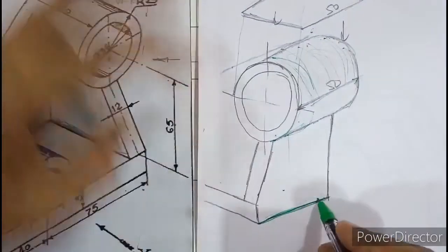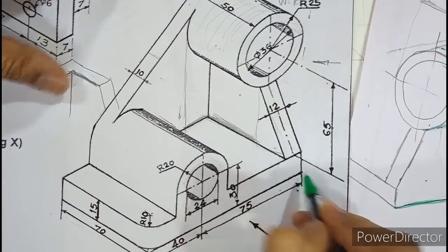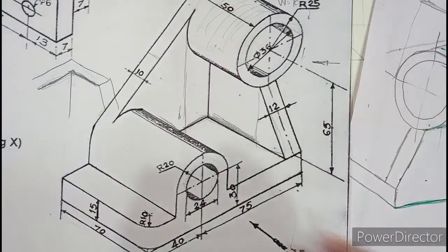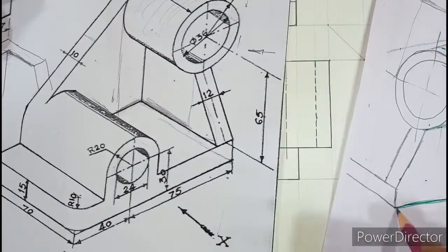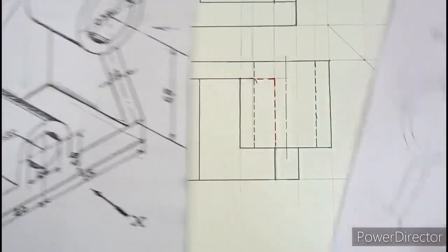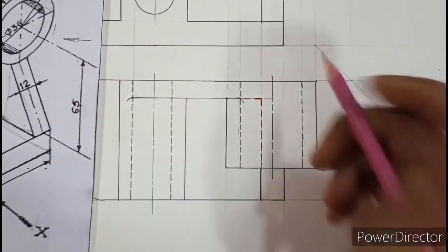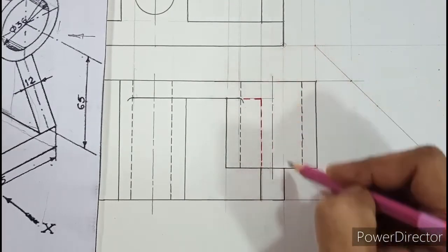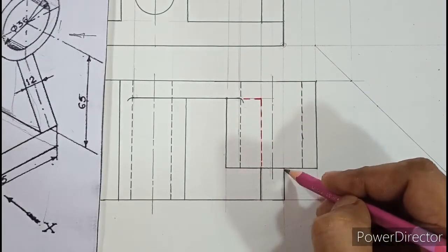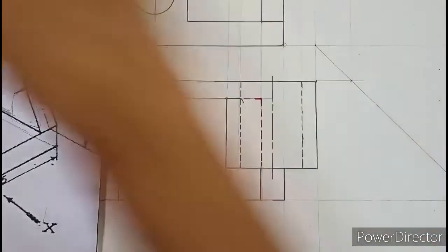This edge, by observation, is 50 mm long. See from this corner. If you look from this corner, there is an edge going inside, isn't it? And that edge is how much? Till the end of the object, that is 50 mm long. That edge in the front view, if you observe, is this one. In projection to that, some portion you already drew dark, and the remaining you need to leave space and draw hidden. I will show by different color.